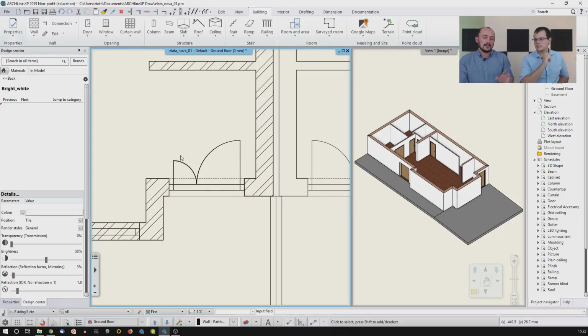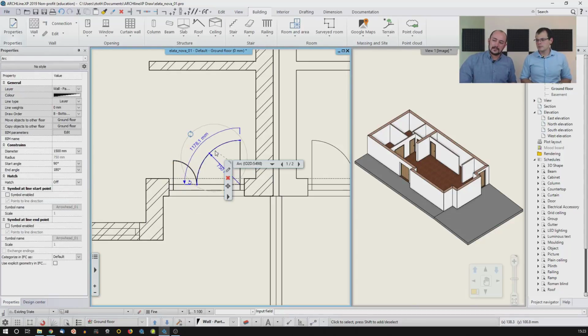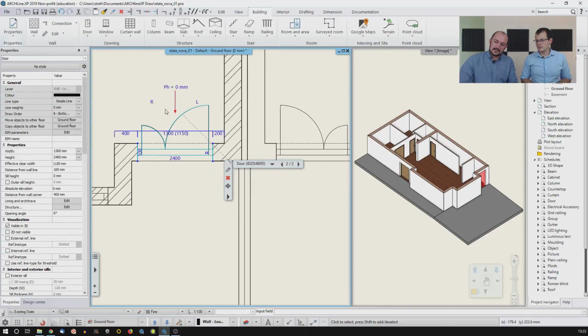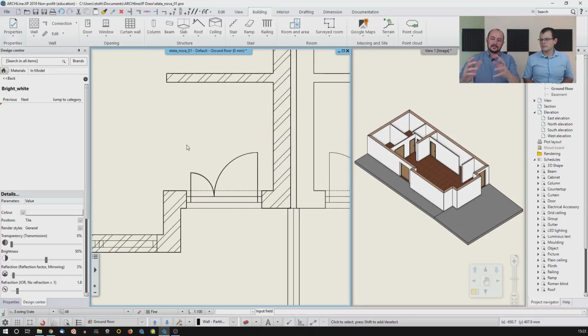And this is when your question comes into frame. When I click here on the door symbol itself, see, now I'm finding the arcs. So I just quickly jump to the door symbol. And this is where you can find this mirror left, right, in, out setting, which, if it wouldn't be perfect, you can just flip it around.